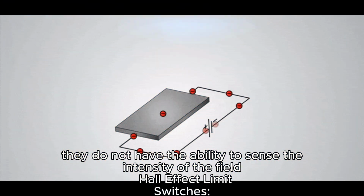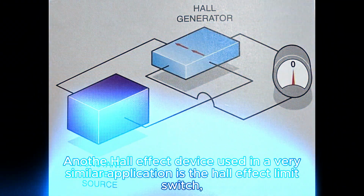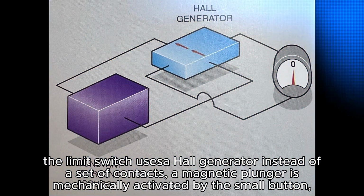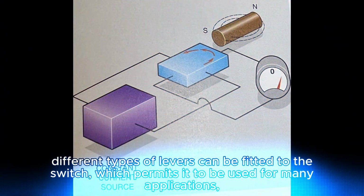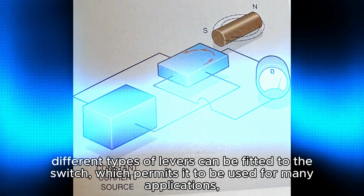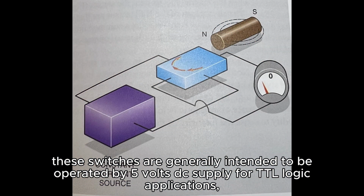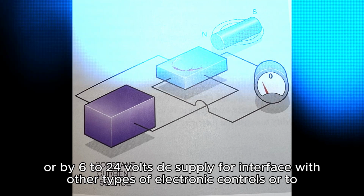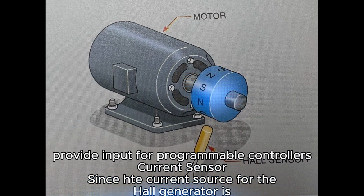Hall effect limit switches. Another Hall effect device used in a very similar application is the Hall effect limit switch. The limit switch uses a Hall generator instead of a set of contacts. A magnetic plunger is mechanically activated by the small button. Different types of levers can be fitted to the switch, which permits it to be used for many applications. These switches are generally intended to be operated by a 5 volt DC supply for TTL logic applications, or by a 6 to 24 volt DC supply for interface with other types of electronic controls, or to provide input for programmable controllers.